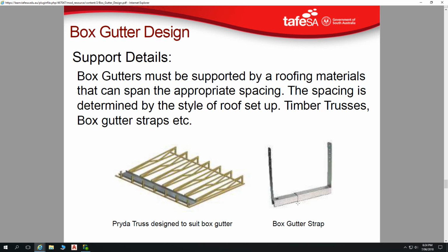So we can start much further back with our equal angle up this height, and our decking underneath, and the box gutter sitting up there, and then adjust that down as it goes through.